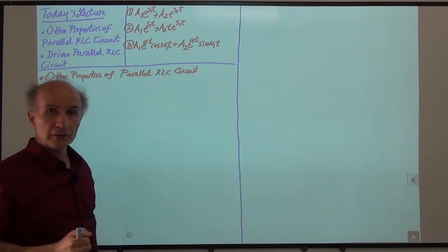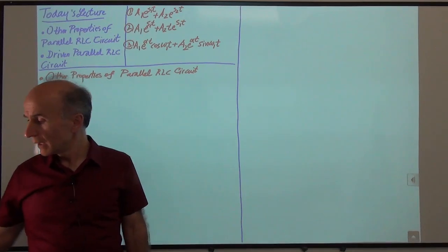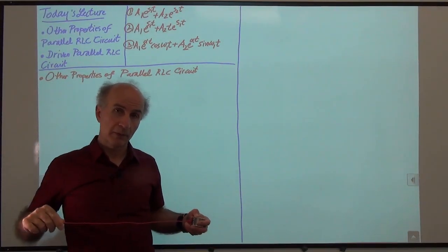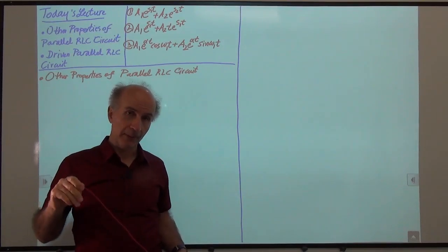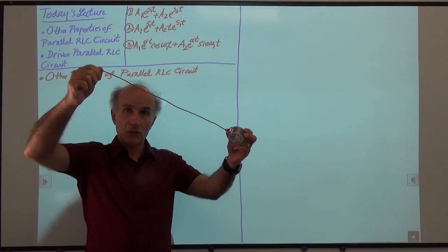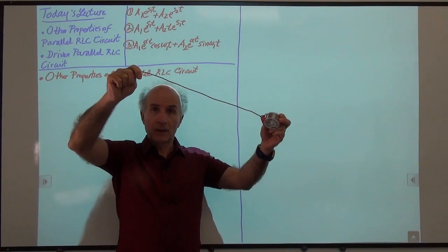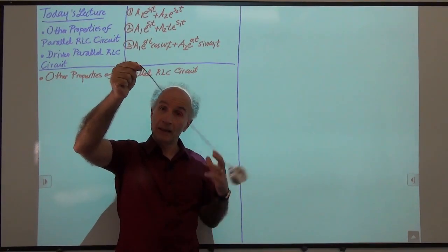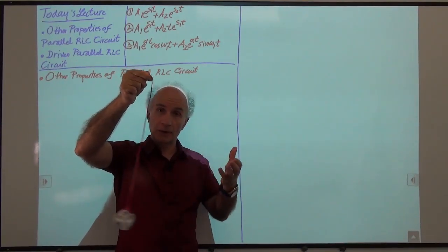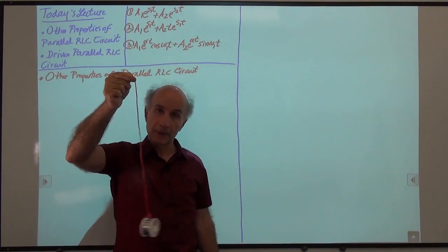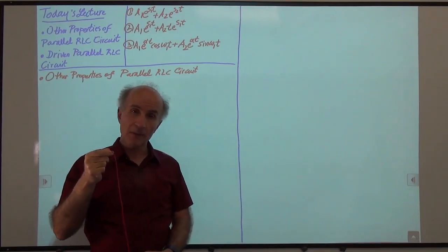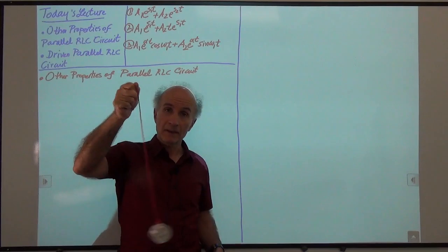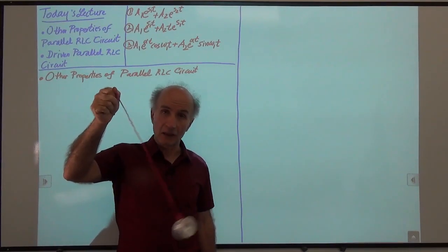So first I wanted to make sure that in our analogy with the pendulum, we are not confused about these three cases. So when we looked at the pendulum response, we saw that when we release it, it goes up and down, it swings, and it decays due to the frictions that we have in the system. But in the RLC circuit, we see that only in one case do we really see this type of oscillatory decaying response, right?